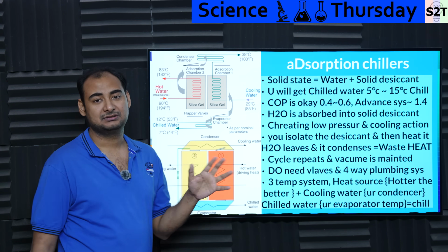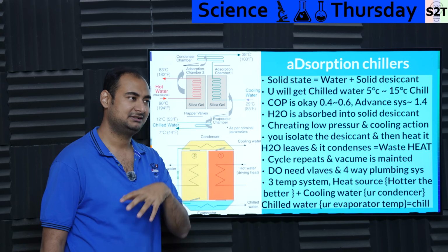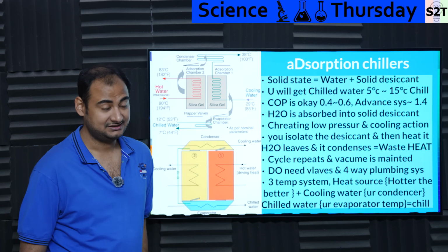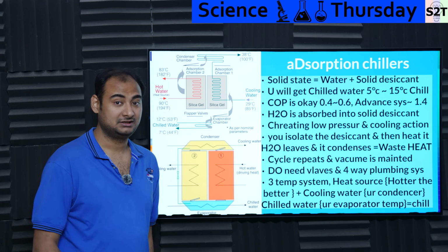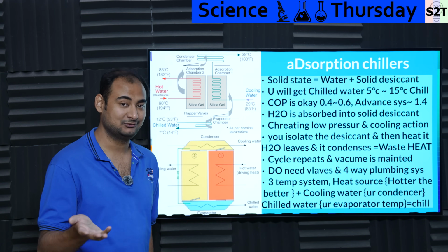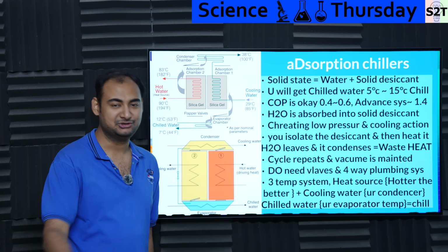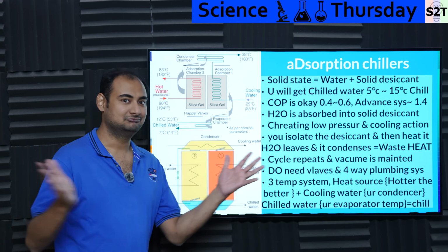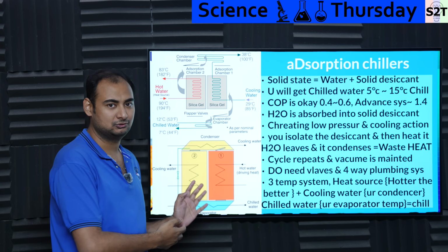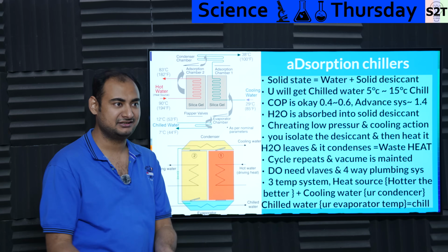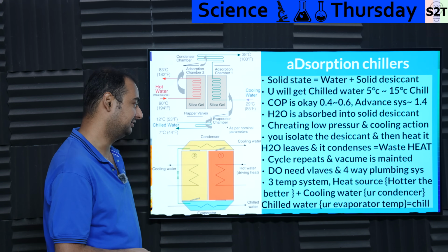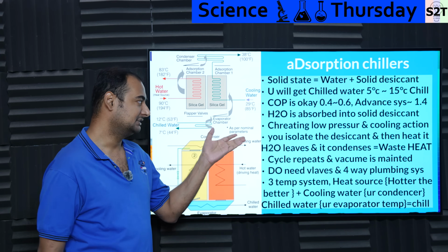And again, for example, let's just say temperature is not that bad, okay? You can live through it. But it's moist, like next to the sea. It's not bad, but because of the humidity, it's brutal. At that point, you run the system in open loop. You can just have a desiccant wheel that can run in open loop, and voila, you are just dehumidifying the air. Much better, and that will be even more efficient. Here you are trying to get the cooling, so it has to remove heat, then condense the water. That will only leach the water away. So it's far more quick and rapid in terms of dehumidification. So this is what we do.